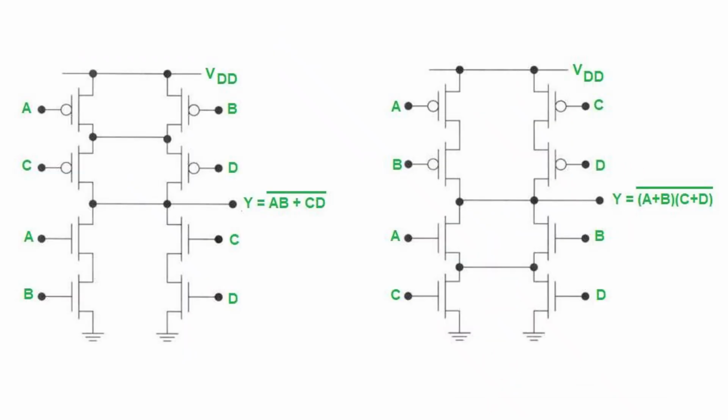So this is the technique. Similarly, this is one more example, y is equal to ab plus cd. So ab, and since there is a plus in between, ab is in parallel and then in series with c and d in parallel, because both are multiplication, so both are in parallel. Just make it reverse: here parallel, then here series, here again these are in parallel, so here these are in series. Likewise, you can see other examples.